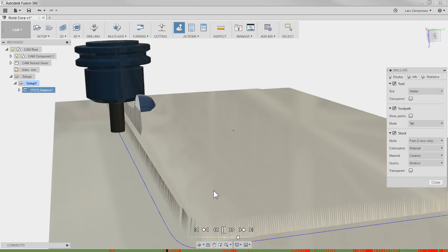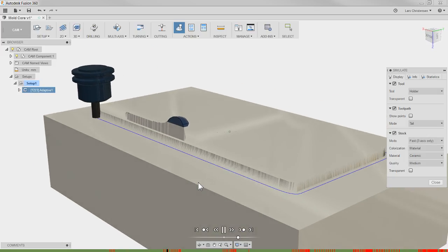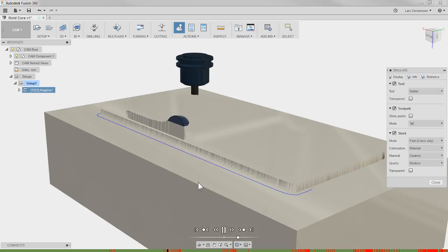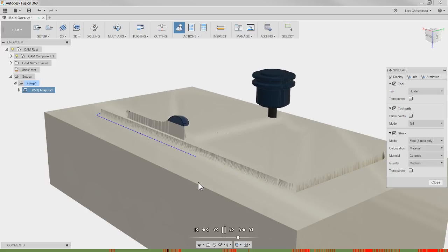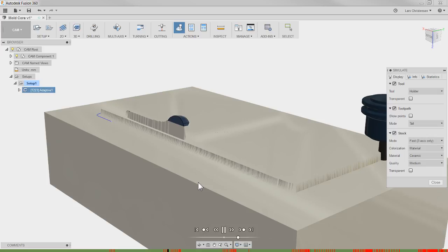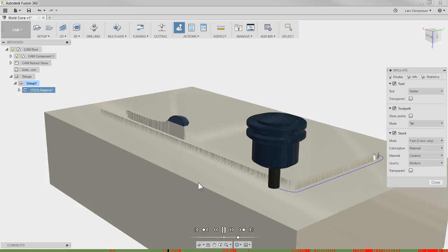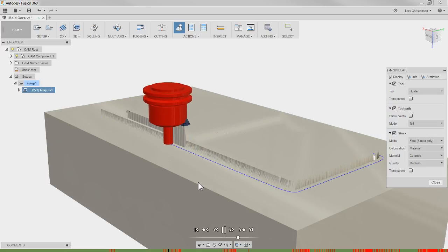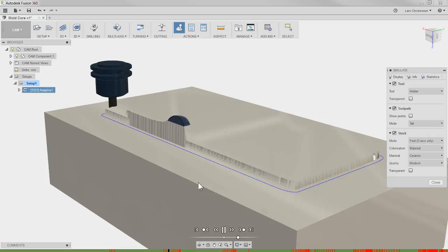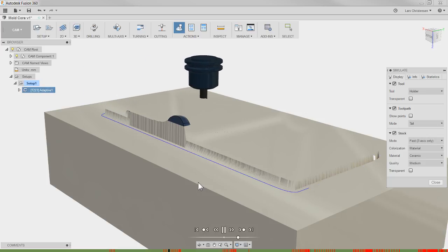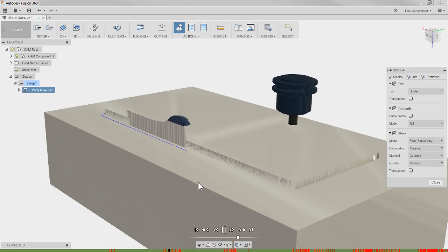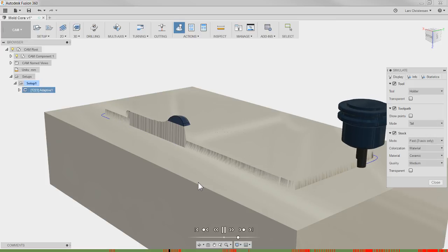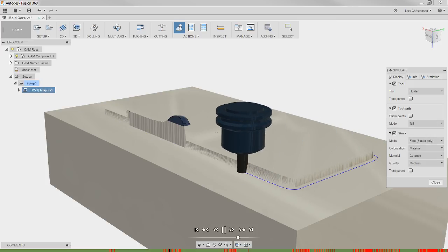This is horrible. So awesome that Fusion has this capability that it gives you a warning that there's some kind of a collision. This could either be tool holder, it could be that you're running out of flute length, or something like that. And yes, you should absolutely pay attention whenever you see that. Matter of fact, when I used to program at Ridlam, I didn't care really what you had to machine.